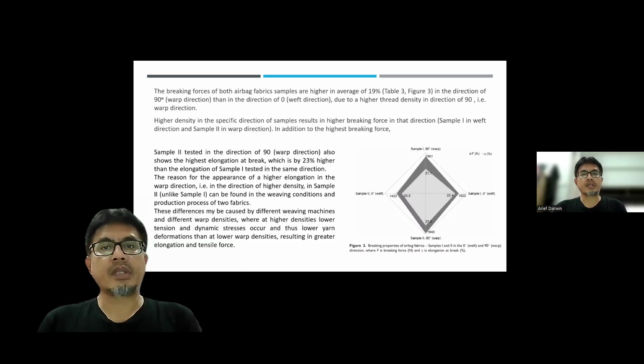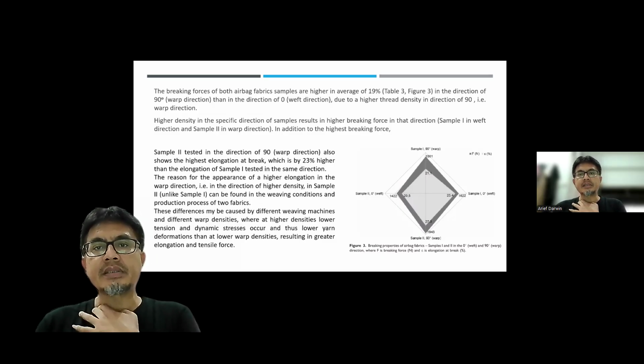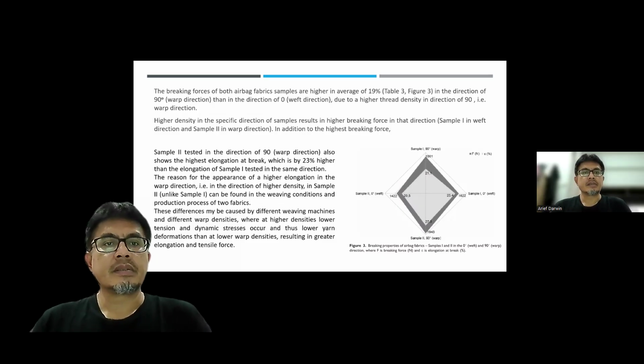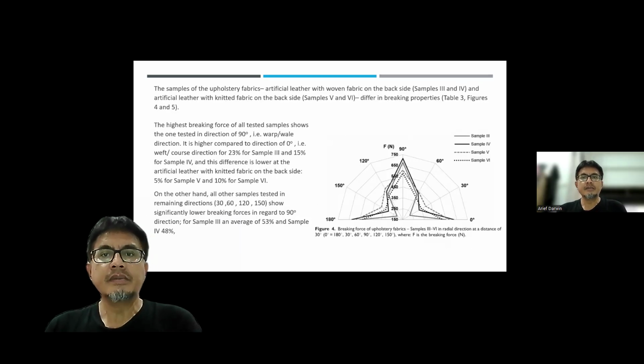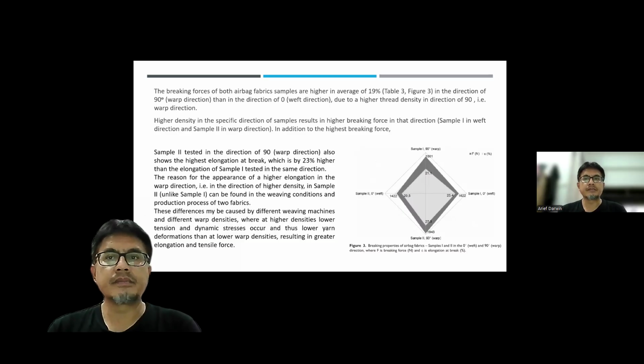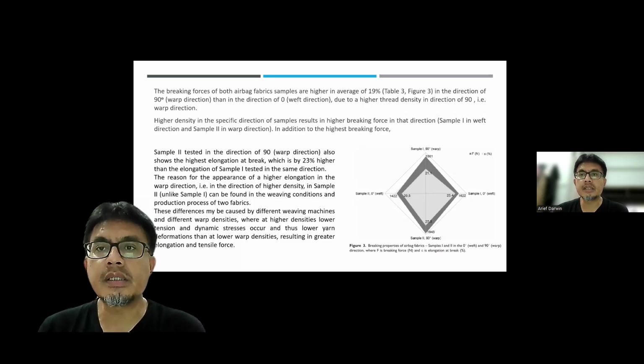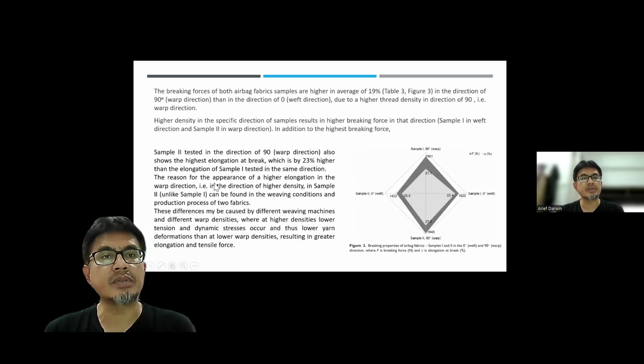Now, we're talking about the breaking forces of both airbag fabric samples, which are higher on average by 19% in the direction of 90 degrees, which is the warp direction, than in the 0 degree, which is the weft direction.